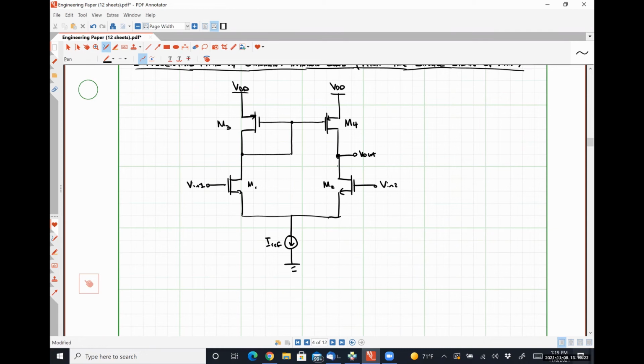And it turns out that we get almost the amount of gain with this configuration as we got by loading it with current sources, except that now we don't have that negative factor out front. So it's practically identical from a gain standpoint, except that it's no longer an inverting amplifier, which is what we would expect with a common source stage providing the amplification. Okay.